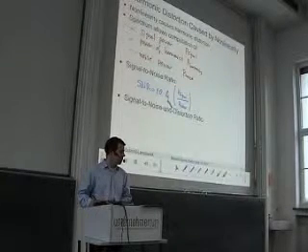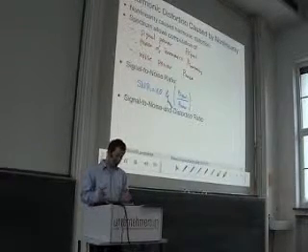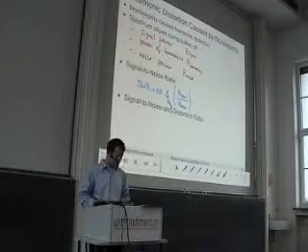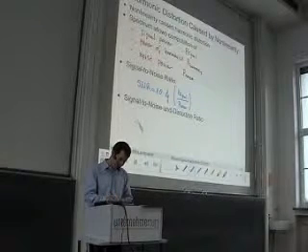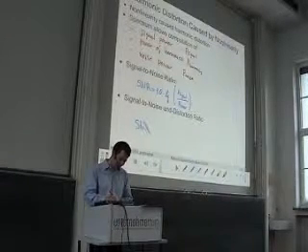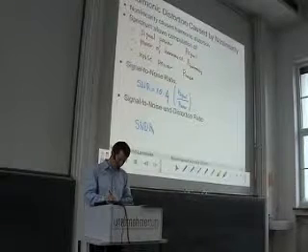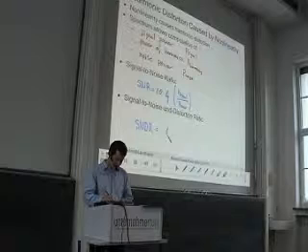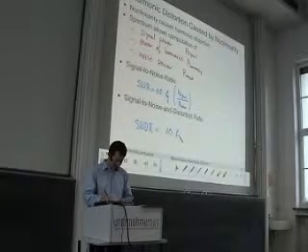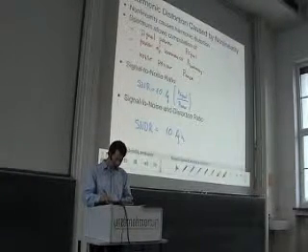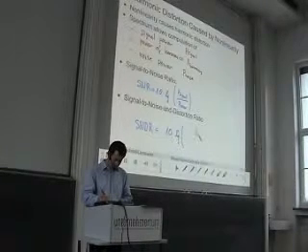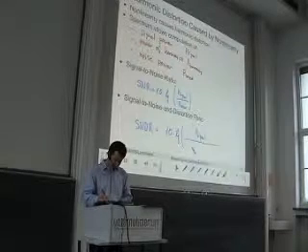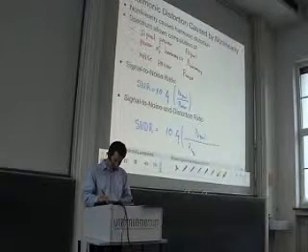Or we can say, well, so far we neglected the harmonics, we also want to take the non-linearity into account, so we calculate the signal to noise and distortion ratio. This is the same definition, however, now we take also the harmonic power into account, so we have here P signal over P noise plus P harmonics.